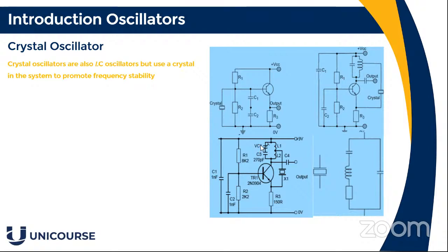But the crystal oscillator, which I can remember using in the 1970s, would give you a fixed frequency, and you could actually change it. But one main advantage of the crystal over the Colpitts and the Hartleys is that the frequency was stable. What we did is choose the actual crystal frequency, which you used to buy, and then put it into the circuit, so you didn't have to do anything, as long as you got the right values of resistors here for this part of the circuit.